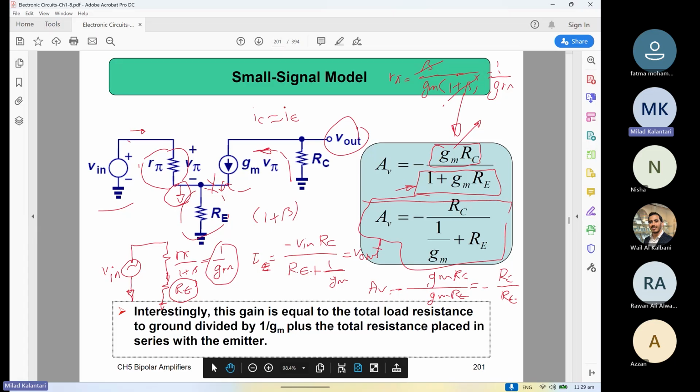But what if you increase the amplitude? Then everything starts changing, because the operating point, the DC currents, change once everything gets very big. Then this GM is not constant, GM is also changing, and this circuit will be very nonlinear, right? If you want good linearity, we will talk about it later. This could help a lot.